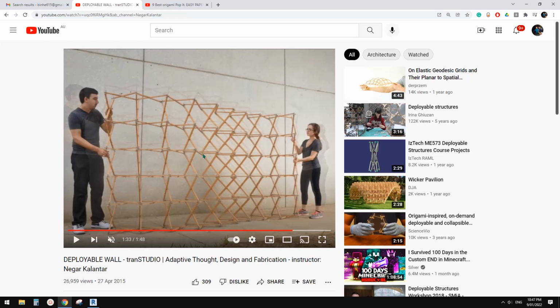We can try to model a little X as an adaptive family, and then place multiple of this adaptive family together, and then create a group of this family, and then use one of them, and we can control the whole thing. Okay, so let's try it.